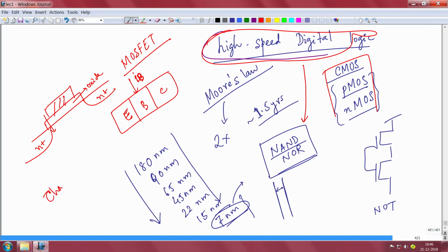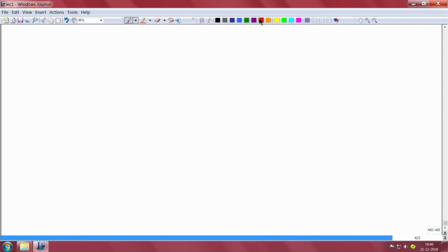charging and discharging of capacitors. Okay, it's all about charging and discharging of capacitors. All these NOT gates, NAND gates, you see physically, in reality they are actually capacitors that you charge and discharge, and the charging time and discharging time of capacitors in this case is the capacitance value times the change in the voltage that you are doing divided by the current that is implementing it.